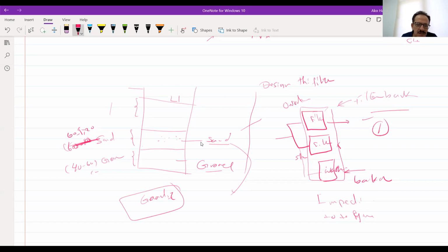I mean, we have it in Iraq, we have it in Ramadi. It's filled with quartz, and it will not be affected by organic matter. How do you know? You have to bring a sample of the sand and pour concentrated HCl on it for 24 hours and see whether there are any losses in its weight or not.